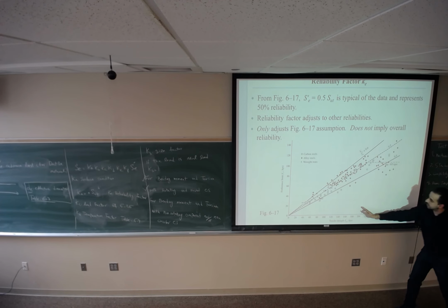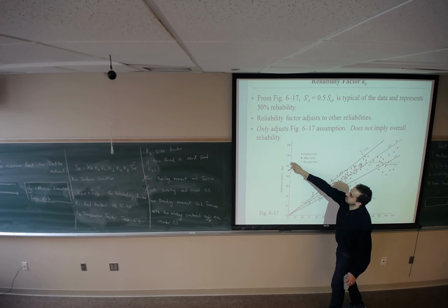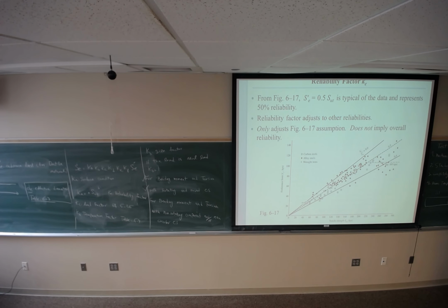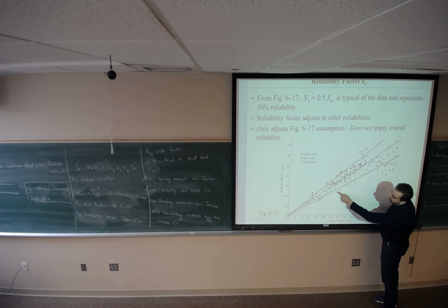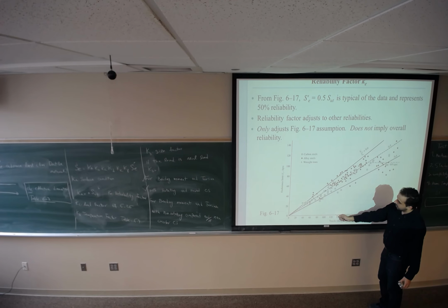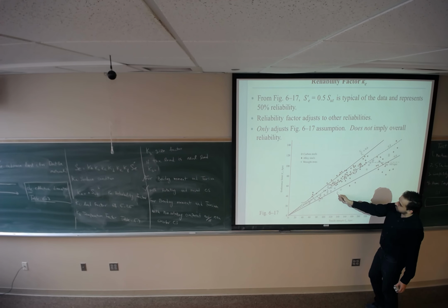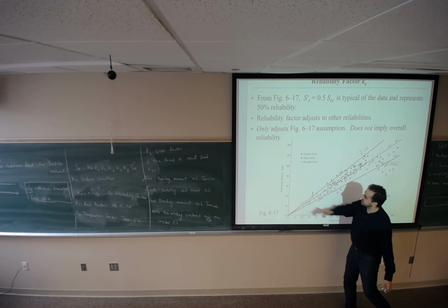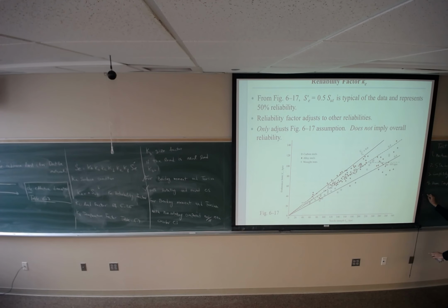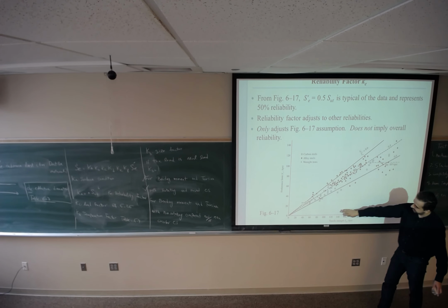And after 200 kpsi, it's going to be 100 for endurance limit. But suppose the material that I have is this one. It's about 130 kpsi. So the test is going to show me the endurance limit is about 45. For this material, I'm going to read SE 45 kpsi for S ultimate equal to 130.